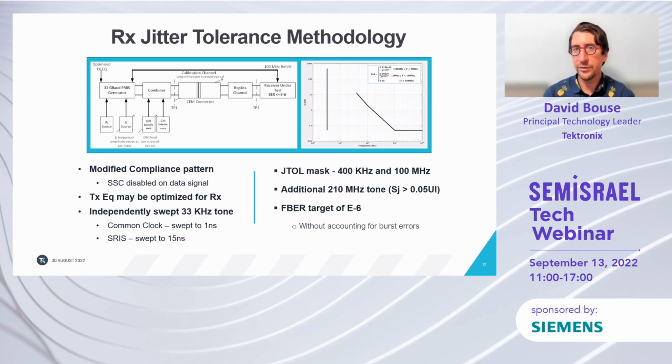So pretty similar in terms of testing to what we've seen for Gen 5, just some new challenges around getting that signal back to the error detector, testing with SSC, and now we're focused on a different BER.